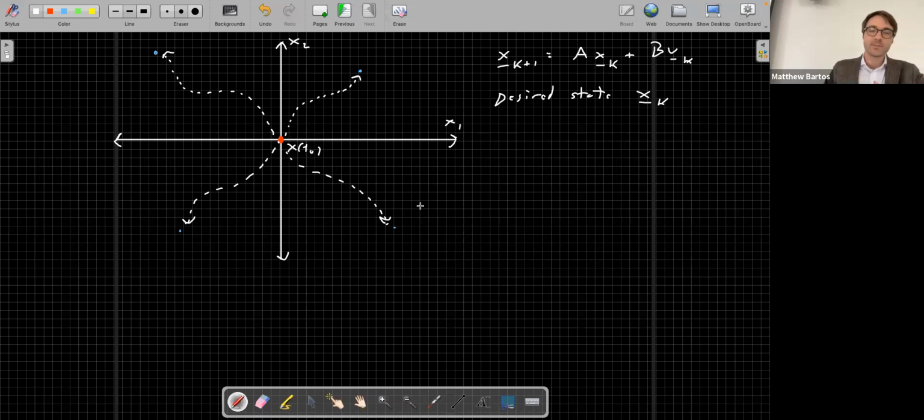All right, so we can iterate from time 0 and just find what comes out. Okay, so we know that x naught, what is x naught equal to for the reachability case? 0. Okay, so we're starting at the origin, so x naught is equal to 0. Okay, what about x at time 1? What will that be equal to? Right, so it'll just be B u0.